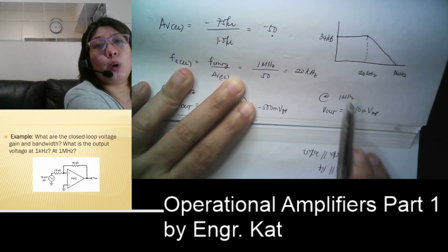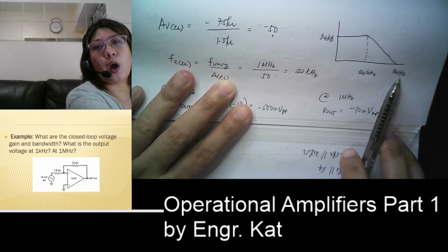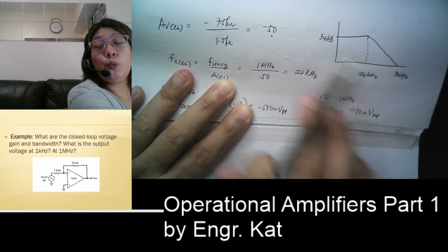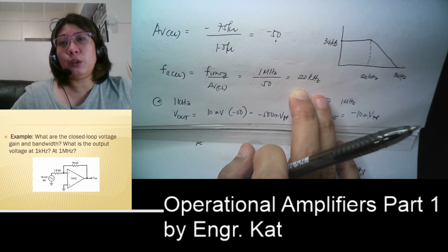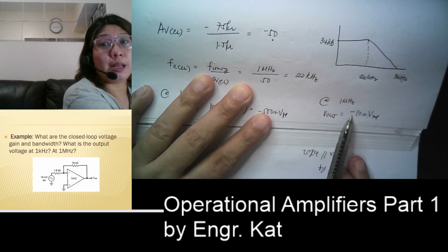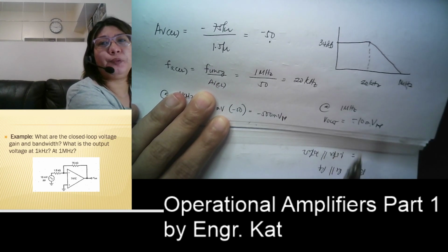Okay, it's not zero because 1 megahertz is the unity frequency for a 741 operational amplifier. So what does that mean? At this point, we just have a unity gain. So what do we mean by a unity gain? So your input is just equivalent to your output, but with a 180 degrees phase reversal. Why? Because we placed your input at the inverting terminal.